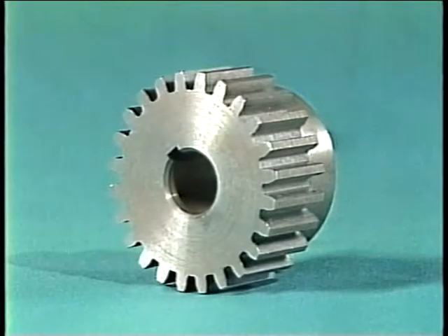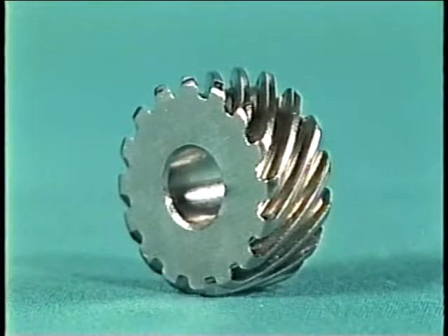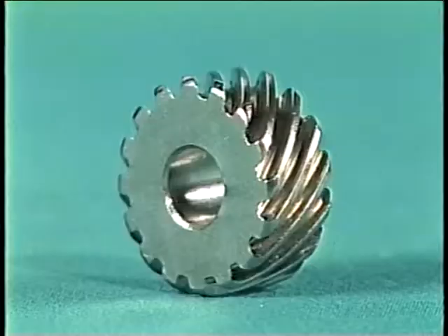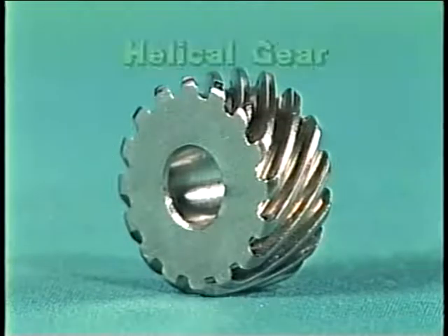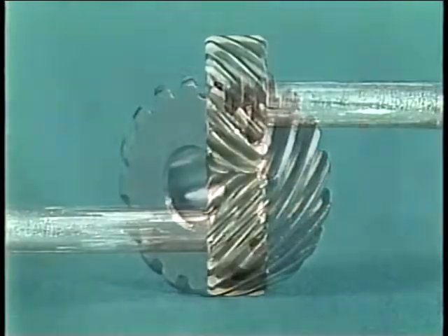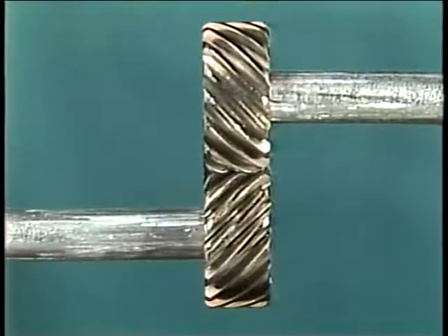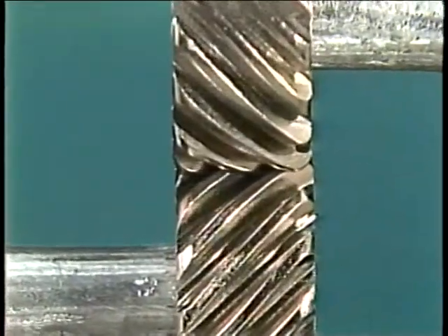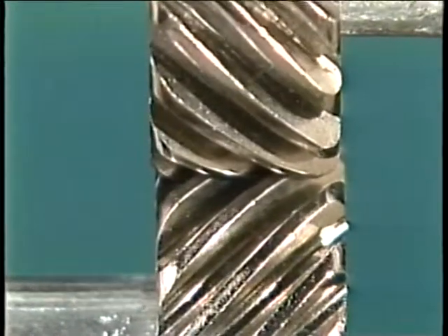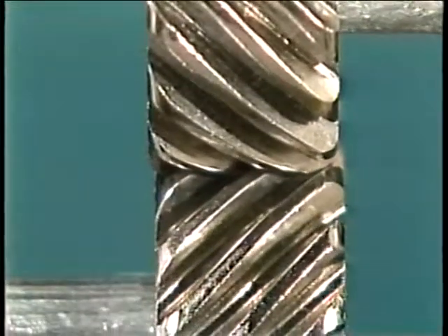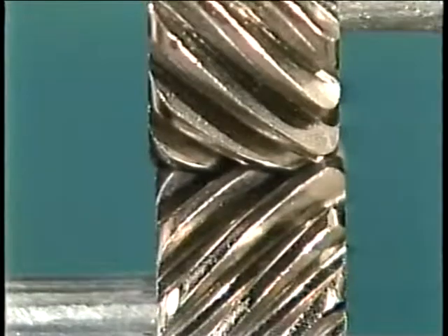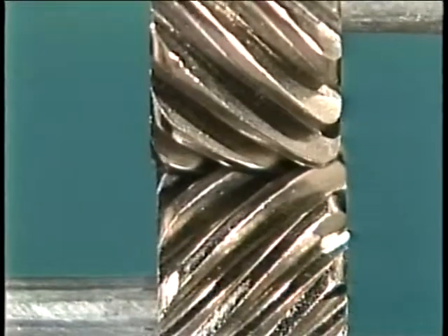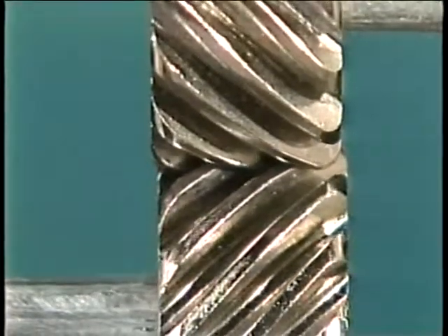As you recall, a spur gear has straight teeth. A spur gear that's made with twisted teeth is considered to be a whole new type of gear called a helical gear. As two helical gears mesh, the contact between the two gears begins at one end of a tooth and extends gradually across the width of the tooth. This allows the gears to run quieter and smoother. This is also true for the spiral bevel gear.